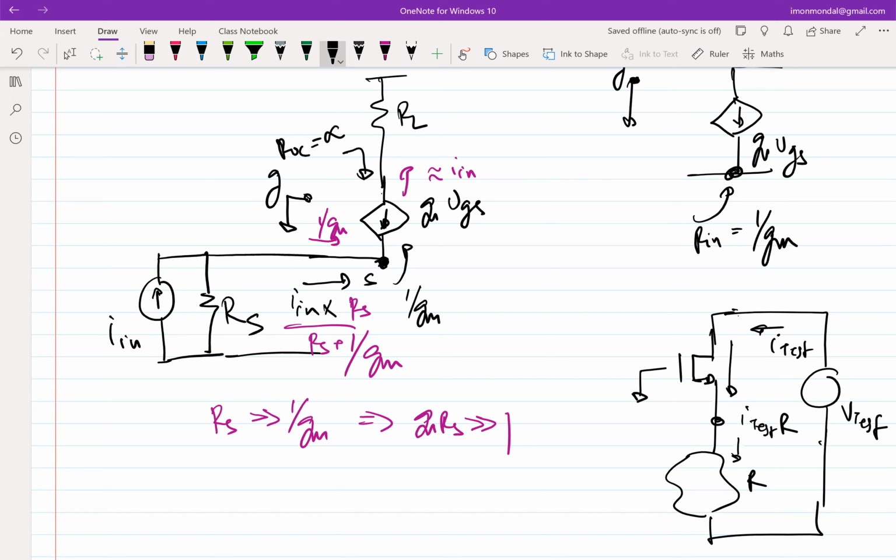And then, which essentially means that it's inducing the source voltage, which means the gm will induce a current, right? What will that current be? This current will be gm times, I mean, negative, but I am changing the current direction and saying this will be gm times I test times R, because Vs is I test times R. Correct?